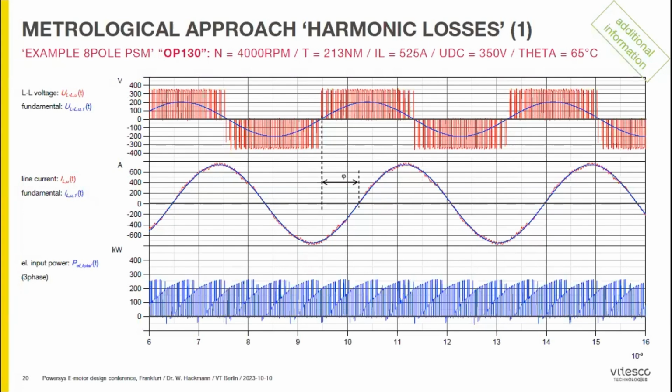And within, you see here the blue sinus. So this is a fundamental component which is inside these. And here in the last graph, you see the time behavior of the electrical power. You see there is a big DC component inside, but there are many, many ripples on this. And this has to be analyzed.